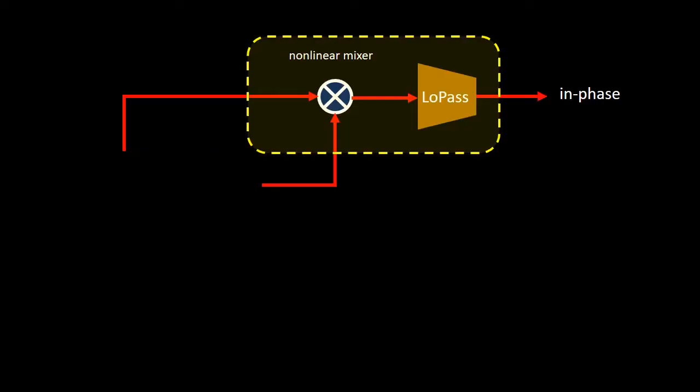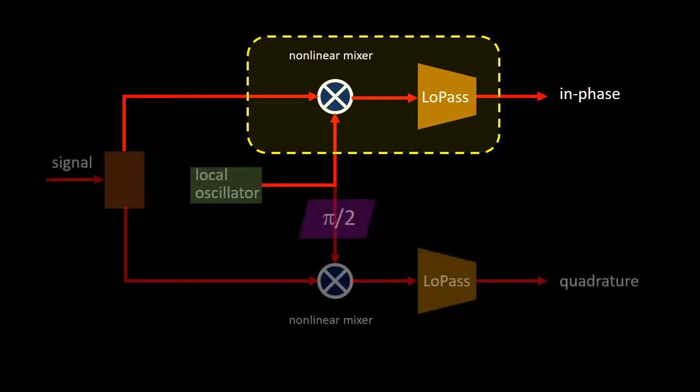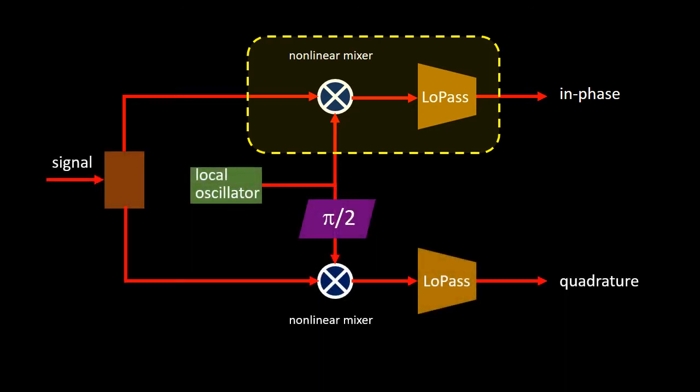The objective of the previous demonstration is to maximally utilize the circuits of Lab 6 for educational purpose. Although strictly speaking, the diode is not a nonlinear mixer, it is useful for the simulation and introduction of the concept. In the theme of communications, what we learn is a part of a common technique of modulation and demodulation, known as quadrature. One of the two carriers in the previous demonstration assumes the role of local oscillator, the other assumes the role of data carrier.